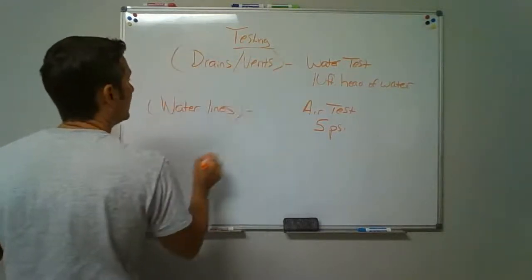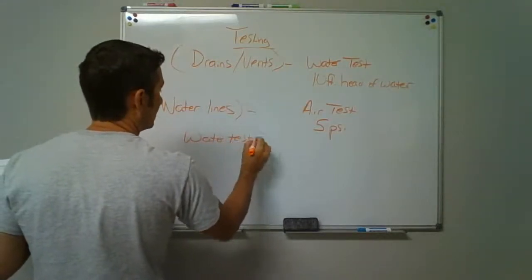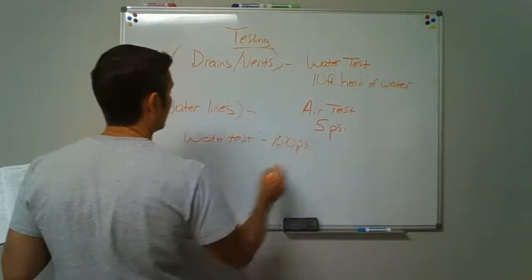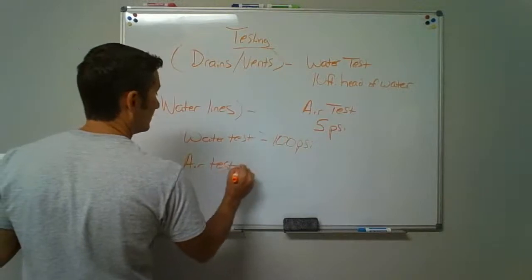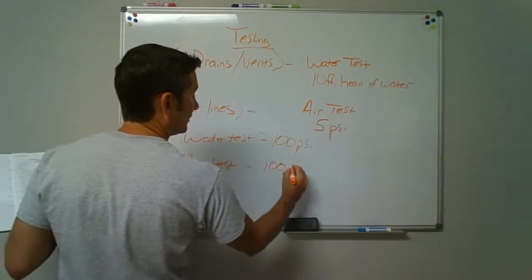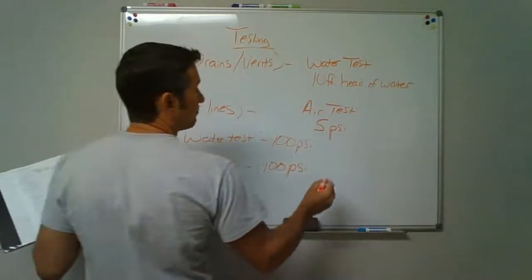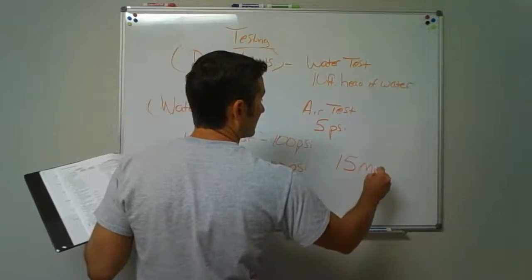We got water lines. We do a water test. It's minimum 100 psi. If we air test, 100 psi. All of these tests must hold for at least 15 minutes.